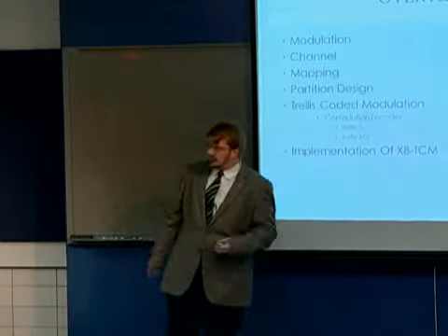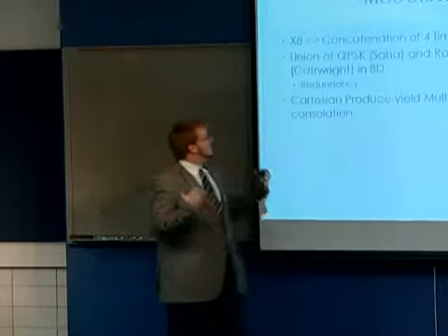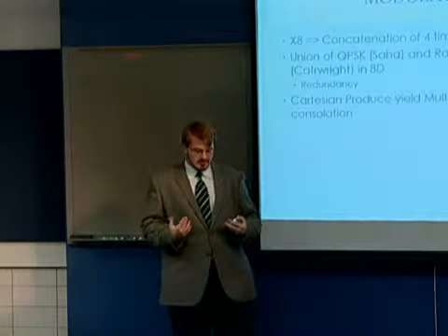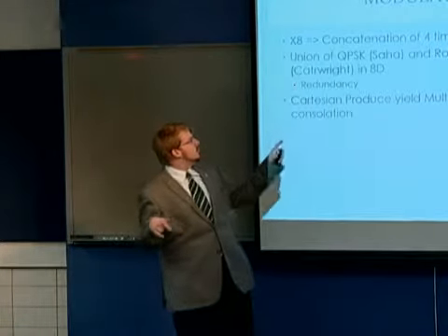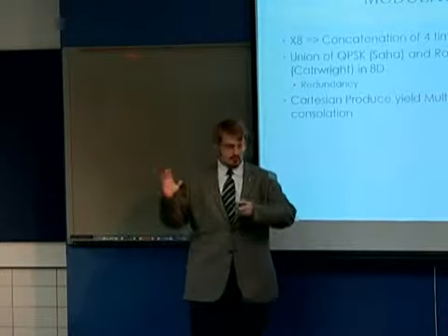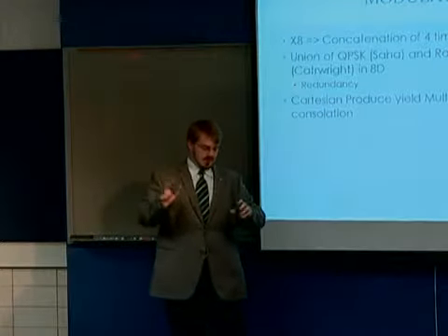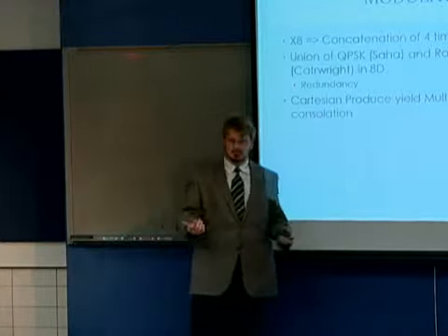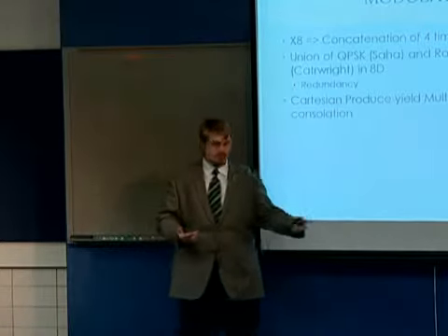and then Tyler is going to talk about the implementation of our 8D. Okay, so modulation itself is where we take bits, information, and we try to send it through an RF channel. For 8D, what that is, is QPSK over 4 discrete time intervals. Every time interval has a real and imaginary component, which correspond to 2 different coordinates. So you concatenate the coordinates together, and then you have 8 of them. So that's why you do it 4 times.